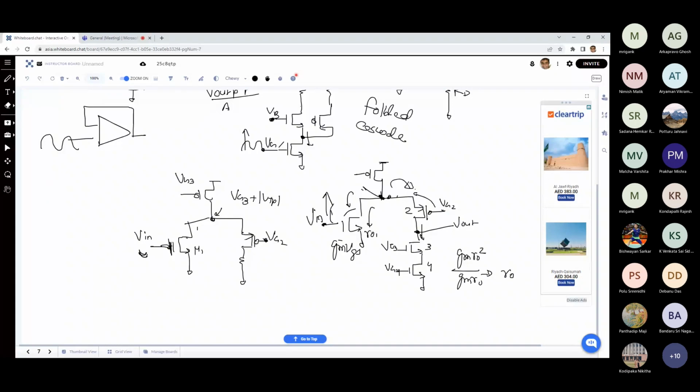So this stage itself provides basically a single stage operational amplifier. That means within a single stage we are able to get a huge gain. So we don't even need multiple stages to get a large open loop gain. So this amplifier has some benefits, and when we use it as a differential operational amplifier, it has basically a simpler frequency response, because the main benefit of this one is that the dominant pole is coming at the output, and it is pretty big because the RC time constant over here is pretty big.